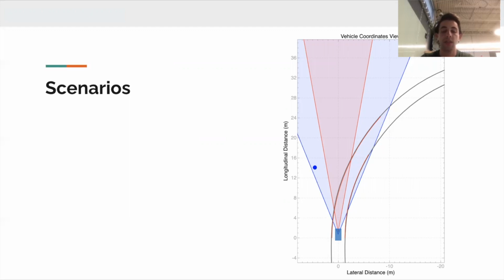There are 2 sensors on the car. The blue field is the camera and the red field is an ultrasonic sensor. This situation will only use the blue field of the camera, since all we need to do is detect the boundaries of the lane, which you can see being done in those red lines. Those red lines represent what the camera is detecting as the lanes. It combines those into a previewed curvature, and using that previewed curvature, the controller can stay on this curved road, which you would see if we had a video.